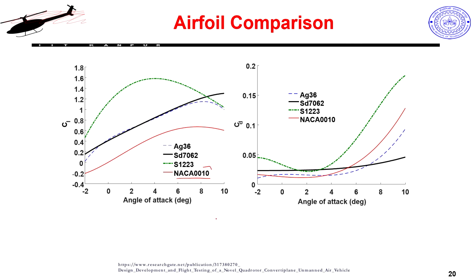Okay. So, if I look at, say, NACA 0012, it means it is 12% thick. This gives you the value of camber and this gives you the location of max camber in terms of percent of chord. Here, 12% thickness is of chord, 12% of your chord length.